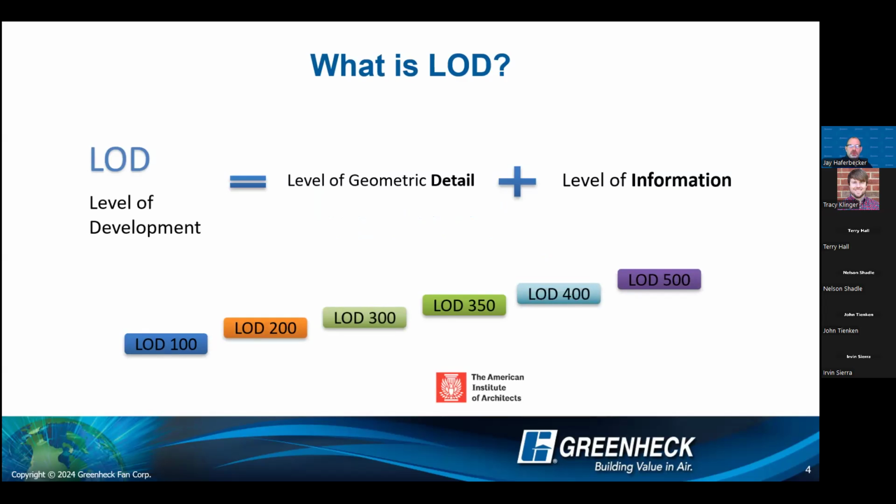The reason I wanted to talk about this is you're probably designing your Revit projects to a certain LOD level, and we have multiple levels of development available, and we want to make sure that we're lining ours up with yours. Because if you're using a lower LOD level than what you're designing to, then you have to supplement that and spend time at it. Or if we're providing a higher level, then in that case, you might be at a liability. So I'm going to run through each one of these LODs real quickly here.